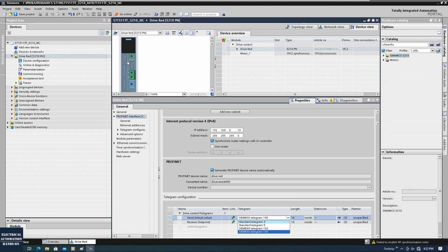So if the servo drive runs the closed loop, it can run much faster than the motion controller, which here is our PLC. Deploying the DSC function into the servo drive can increase the closed loop positioning performance. So usually with a Siemens drive and a Siemens controller, for example a S7-1500 standard PLC or S7-1500 technology T CPU, I highly recommend you use Telegram 105 and the DSC function. So we pick 105.